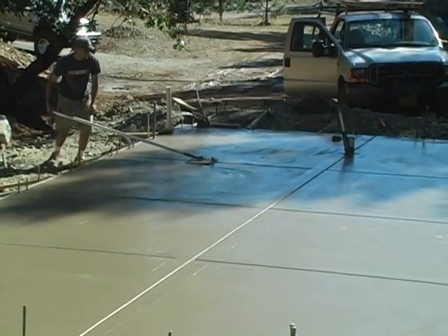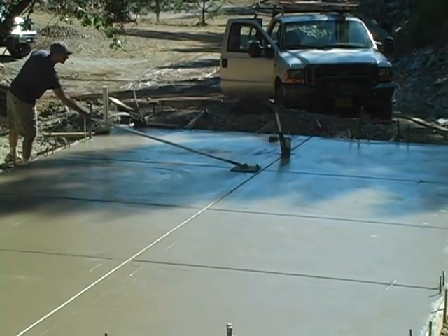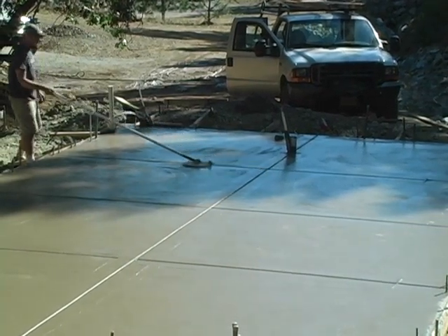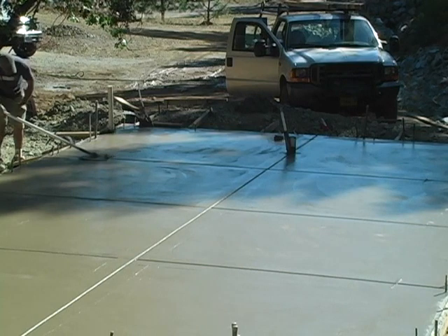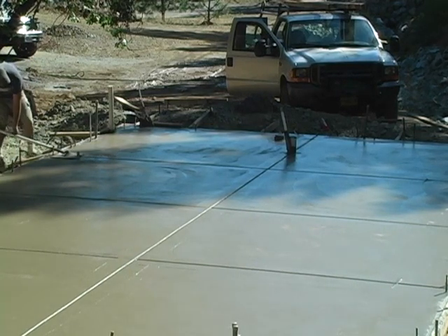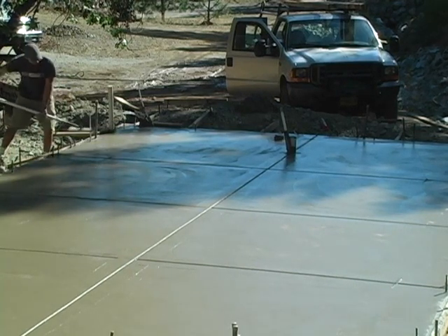Now here we're just going to go back and forth over these grooves. You want to keep working this stuff as the concrete's curing. Again, we've sprayed the con film on there, so we've slowed down the cure process, which gives us more time to work these grooves really clean.